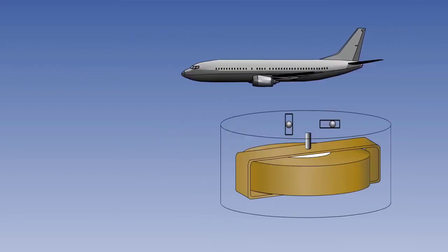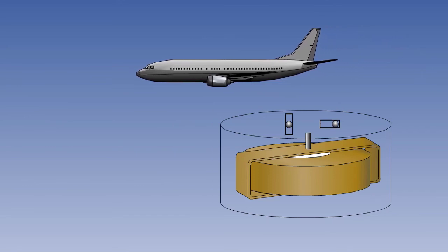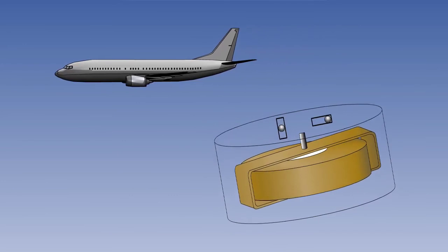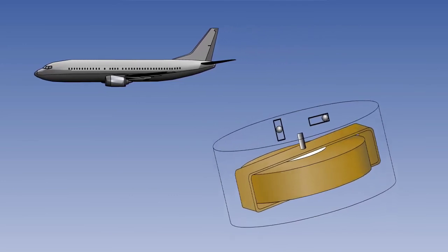As we have seen, acceleration errors are minimal in the electric artificial horizon. However, there would still be a tendency under acceleration for the mercury in the mercury switch to close its electrical circuit as a result of inertia acting on the mercury. This would result in the pitch torque motor falsely precessing the gyro assembly out of vertical.